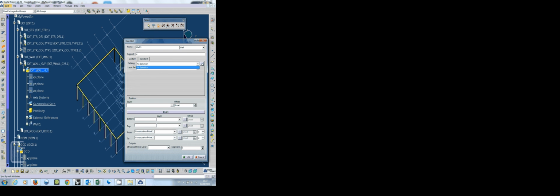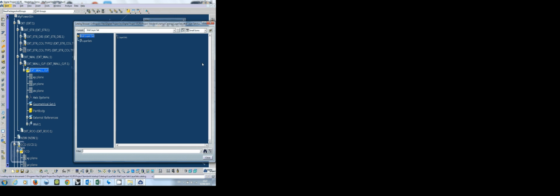And you can select the kind of wall. I'm using, say, structure and envelope. Double click. It gives you the build-up layers. It is loading from the standard catalog. Loading, first time.